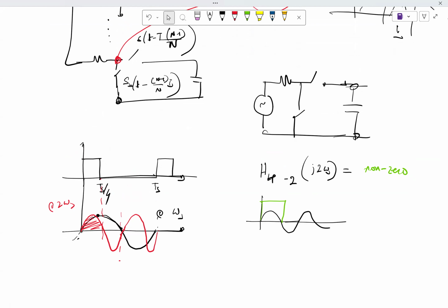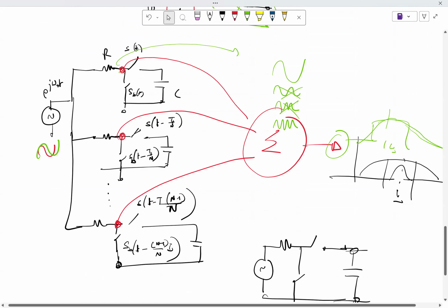so if this is non-zero and you multiply by s of t, obviously you are going to get non-zero. So this does not naturally imply it's bandpass filtering. What this is saying is that this very action of switching is creating tones, sidebands, and if they are close by, then the lousy bandpass filter that should follow should also have higher roll-off than if the tones were not there.